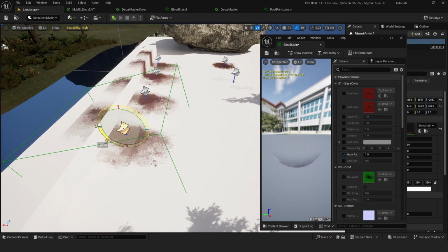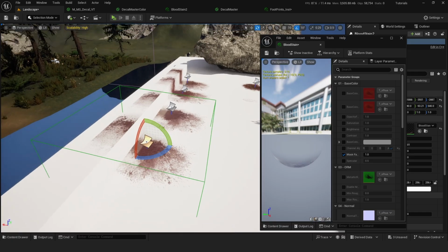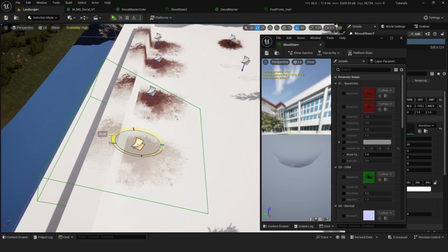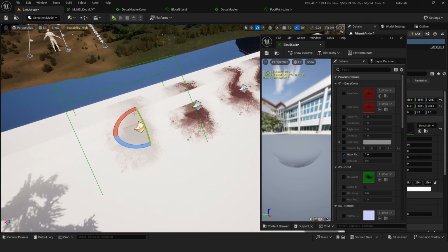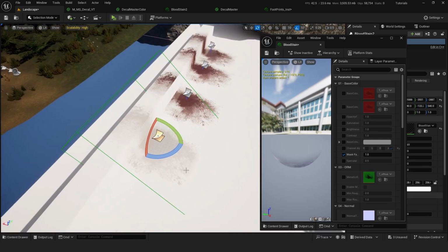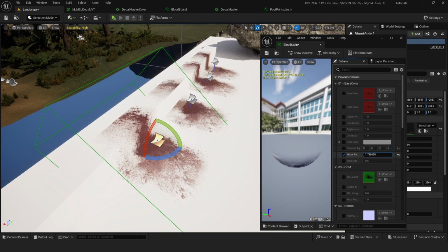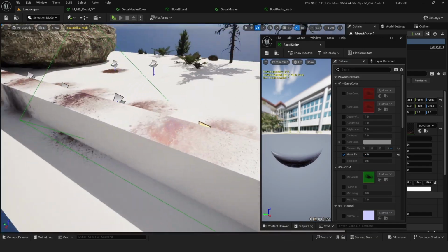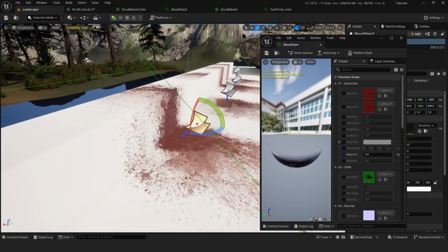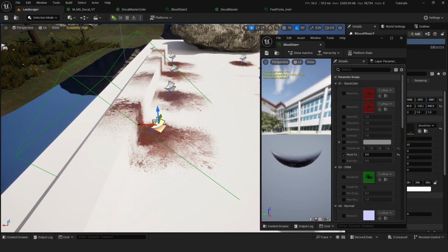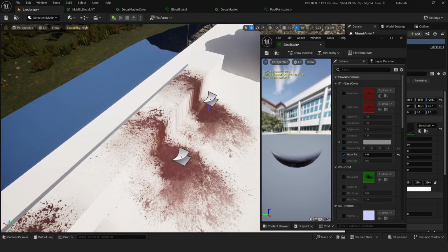If we go back to where it was, the decal is fully visible as soon as we start tilting it, because it doesn't correspond with the angle of the surface. It starts disappearing, which is why we have this control. We can increase it so it looks exactly how we want it, but we still don't have any stretch marks, or it's not leaking through, unlike the ones that we have by default.